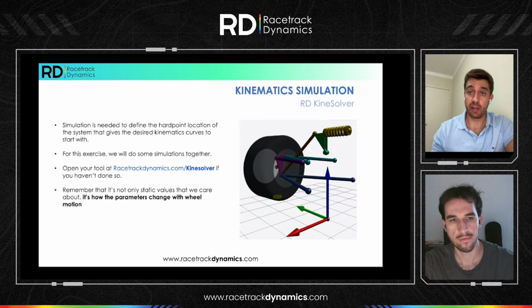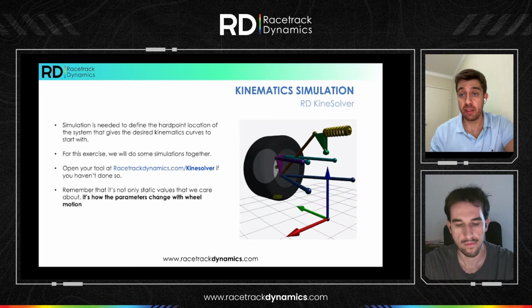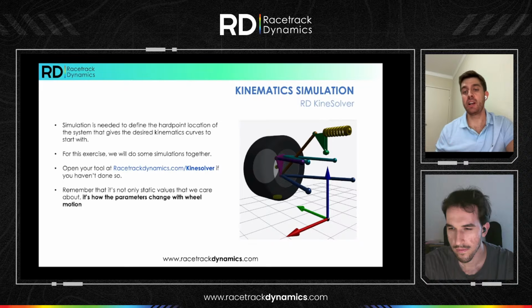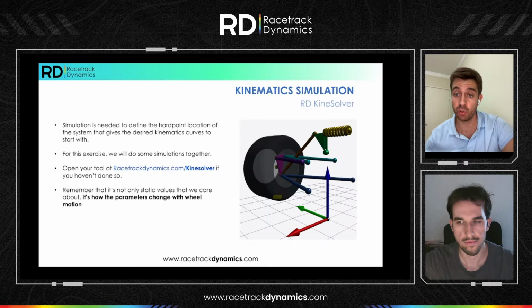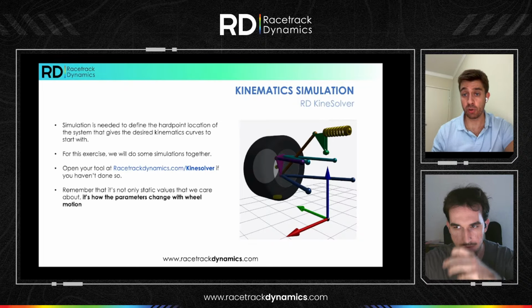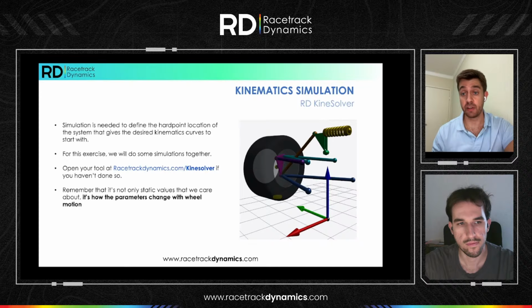And then we're going to talk about kinematic simulation and our RD Kinesolver, which we're going to play with together in this seminar, in this workshop. So we understand a little bit of what we're trying to do. We understand suspension basics, but now we need simulation. We need a tool that helps us define where these points need to stay in space, so we don't need to calculate everything with trigonometry every few iterations. That's why we have kinematic solvers. And now we will run a guided exercise together.